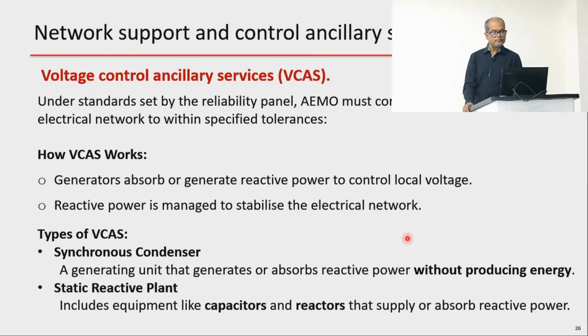Now again, how does that work? As you know, every generator has an automatic voltage regulator. So when there is a change, the generator tries to absorb or generate reactive power to control the voltage, and as I mentioned, reactive power is managed to stabilize the network, mainly by controlled capacitors and reactors.